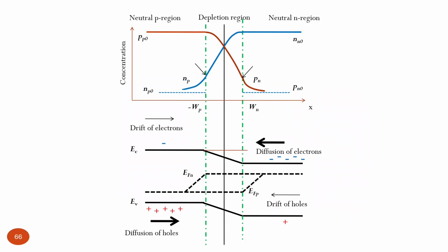Yes, this one. As we mentioned before, we are interested in two parameters. First, the profile of the minority charge carrier distribution. We already learned something about it because we considered this specific case of minority charge carrier diffusion from the illuminated to the dark part of a p-type semiconductor, assuming a low level of excitation.